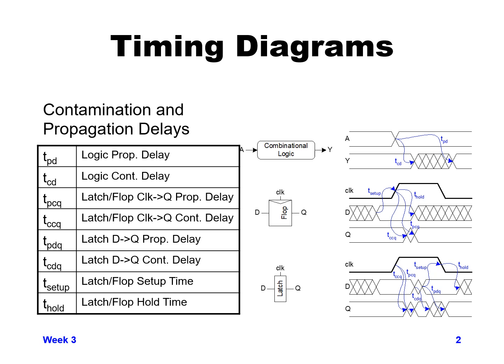If you're in the middle of D changing, you don't know whether you'll get the value before it changed or after it changed if it's not stable when you're sampling it. So T setup is how much time D needs to be there and stay stable before the clock rises.